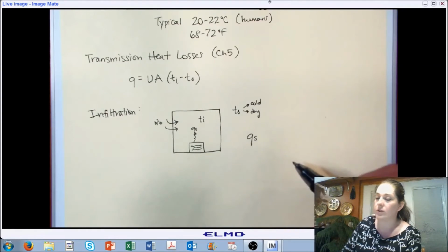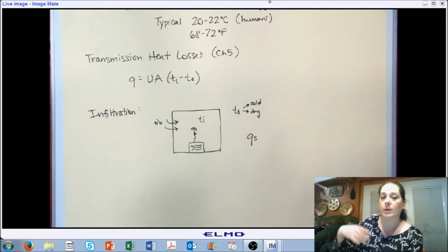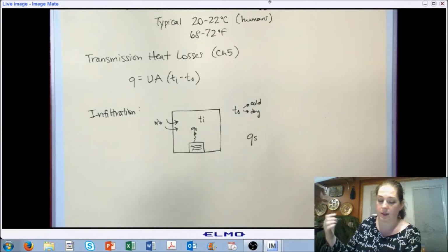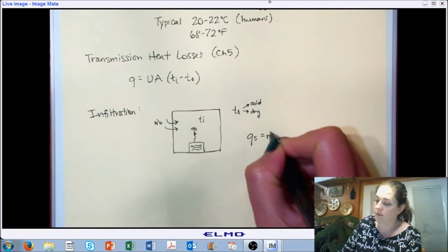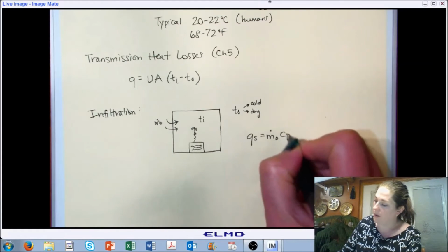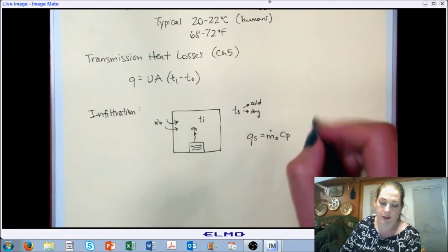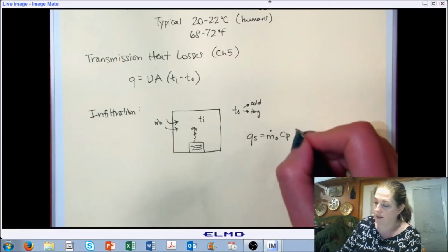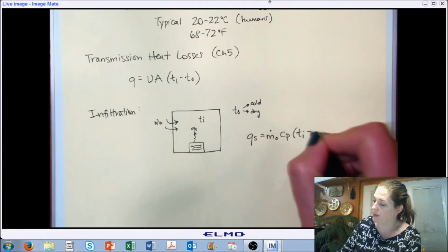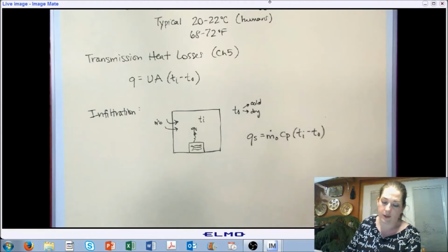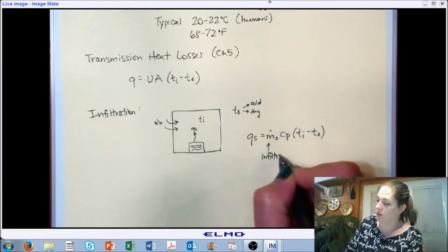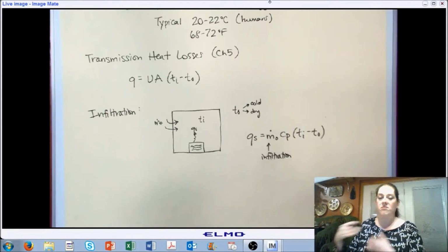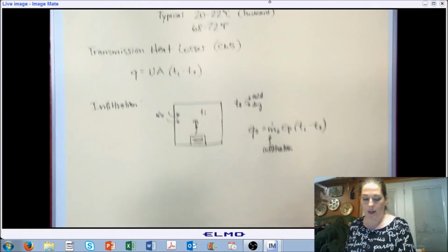So the amount of energy supplied, which could be by occupants or by the heating system that we select, the amount that's required due to infiltration is related to the mass of air that's infiltrating into the space times the properties of the air, much as we've seen before. We've seen this equation before. But just to show that we're following in that same thought process, we're revisiting it.